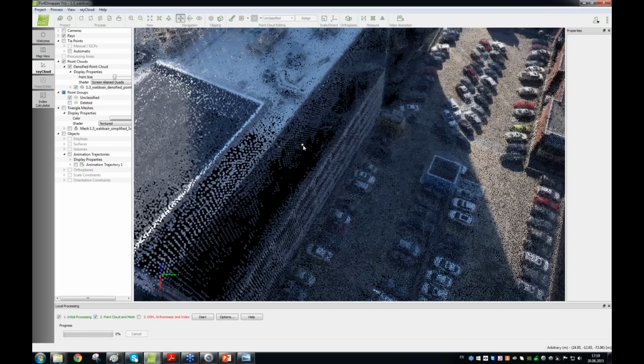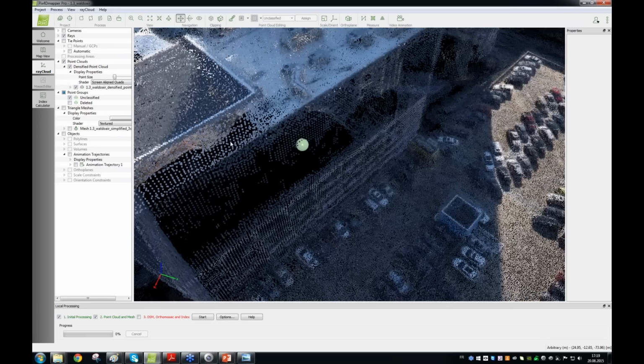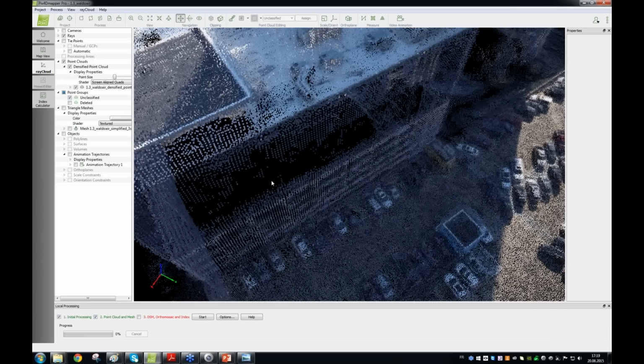And in the 3D point cloud, you clearly see that you have fewer and fewer points, and here you don't have any points. So this gives you an indication that the software was not able to reconstruct the information there. It doesn't tell you that it's a hole, it doesn't tell you it's empty, but it does tell you that there's not enough visual information to compute anything here.